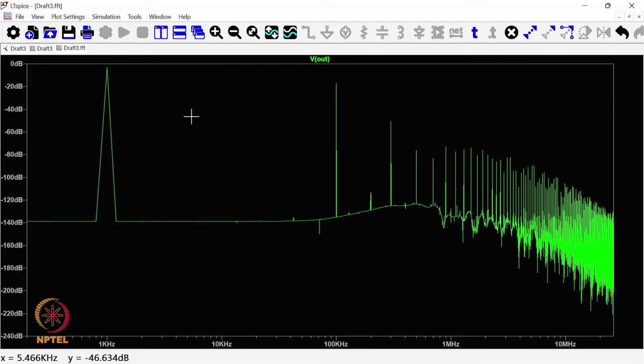So, you put a low pass filter. What is a low pass filter? It filters out the high frequency noise; it only passes the low frequencies. As the name says, a low pass filter passes the low frequencies, which is here at 1 kilohertz, and it removes all the frequencies on the higher side. So, now we want to put certain components so that the circuit behaves like a low pass filter and removes all these frequencies.